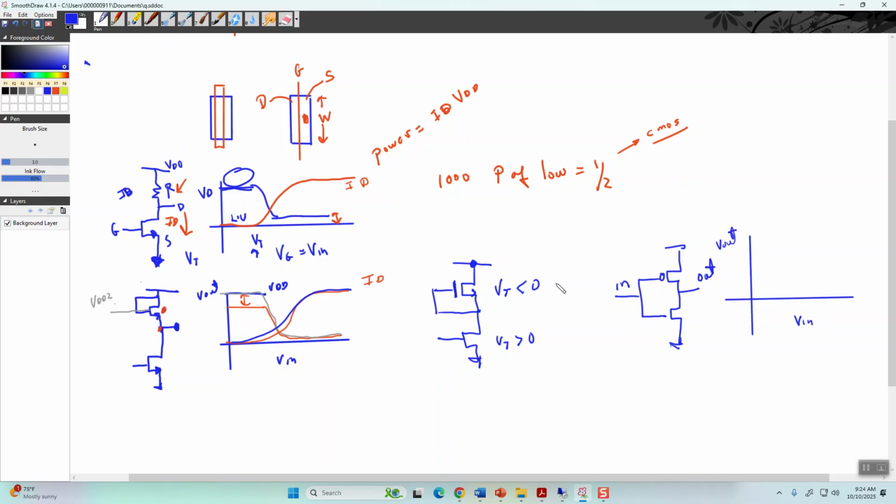Now, before we always had a load transistor that we were dropping a potential across to get our output low. What happens here is that with the PMOS, right, that conducts current when the NMOS is off, and the NMOS conducts current when the PMOS is off. And so what happens is you don't really have a load per se.